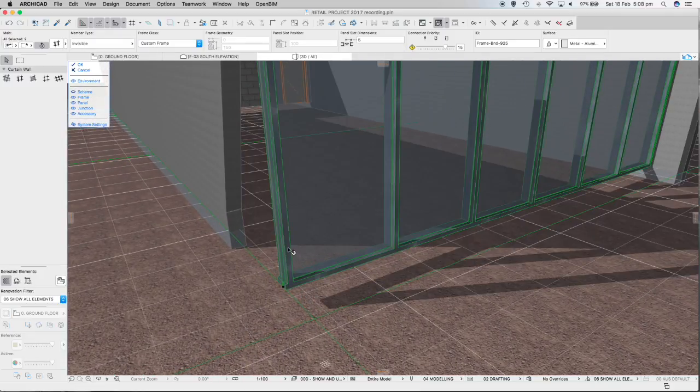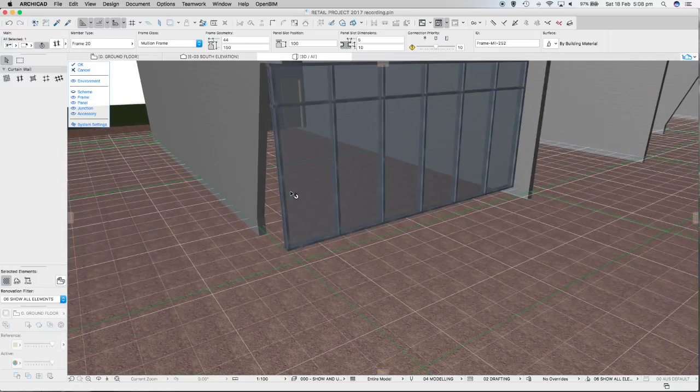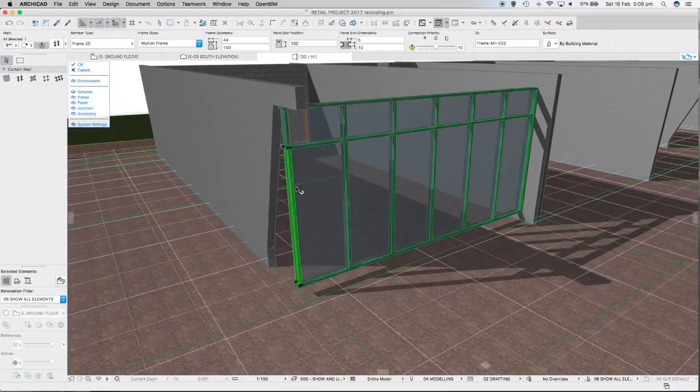Yes, we did have a double mullion there, but that'll probably serve our purposes pretty good there. So I'll click on that again, and then you can see that we've got one of these tools again. So click that to select all of them joined, and I'm going to make the frame geometry 0 and the frame type invisible.